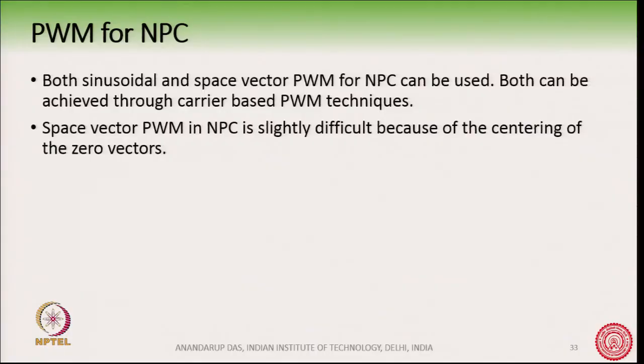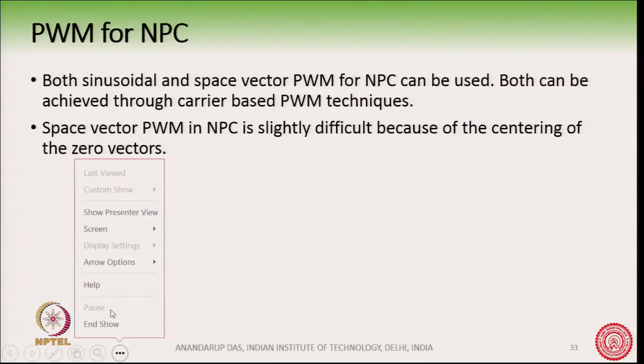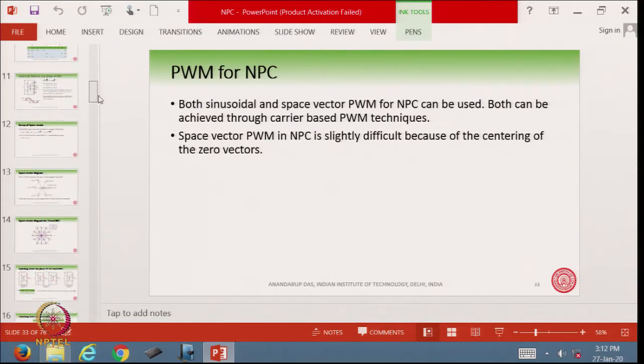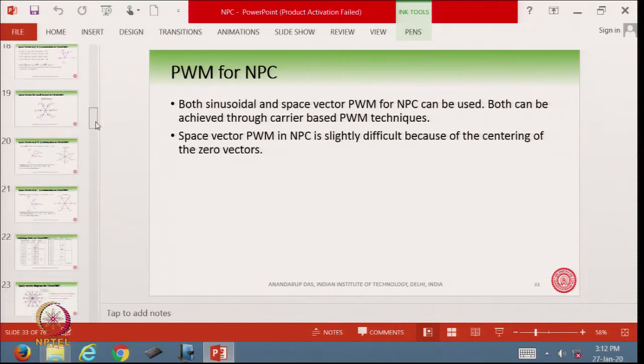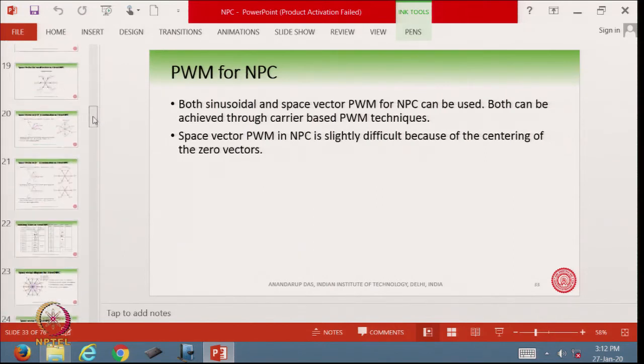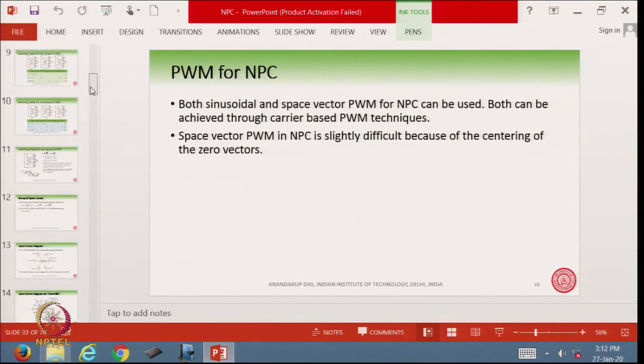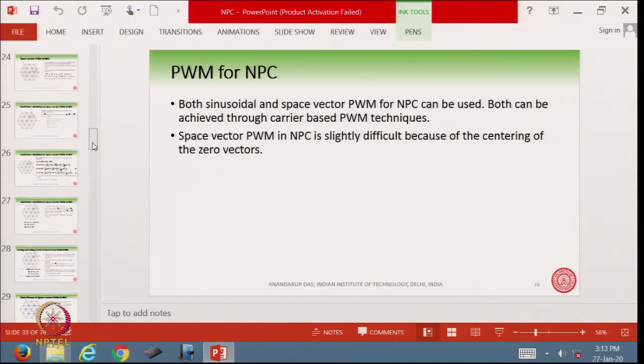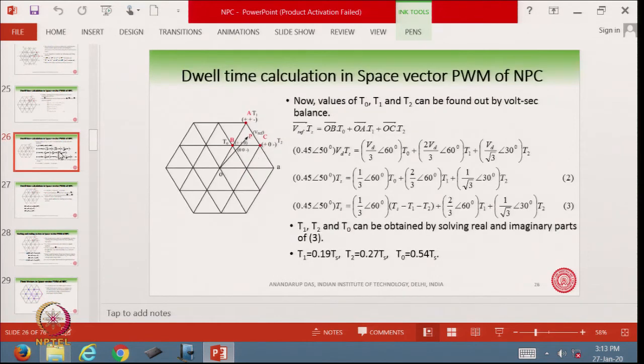If you want to see the timing based PWM strategy, you can refer to an earlier slide where we talked about T1, T2 and T, and find out how we can calculate the timings for the 3 nearest vectors.